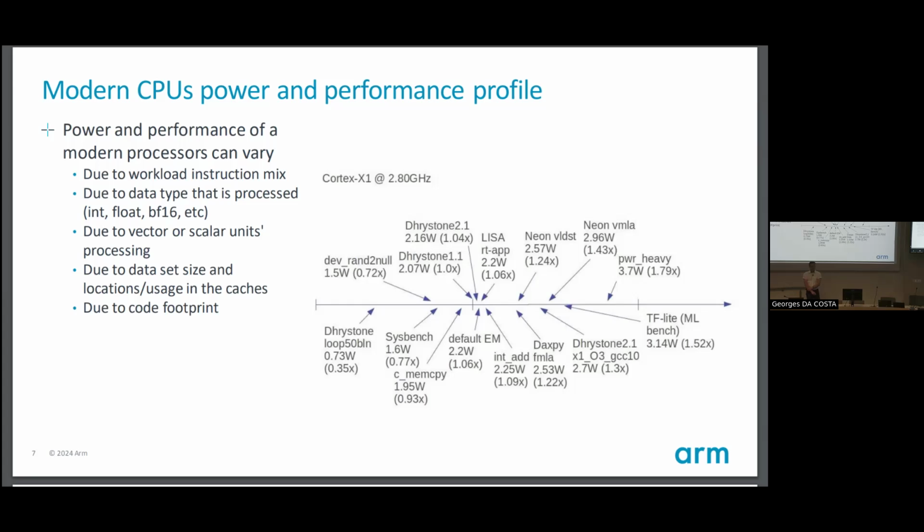We currently have one value in the energy model, here for that particular Cortex-X1, 2.2 watts, and we try to use that value for power estimation from the EAS hot path simulation point of view. But as you can see, we are not always right about the average power that we consume at the OPP. That's why we run offline post-processing when we record a trace.